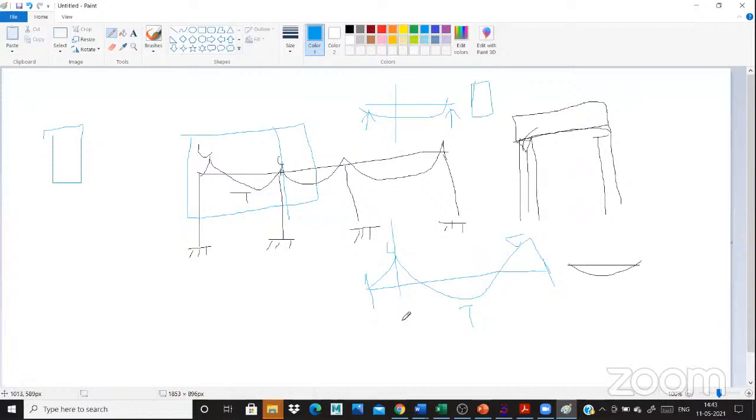The first cross section is for this end, this is AA, our cross section, and the next is the mid span. This is BB for cross section. This is CC for my cross section. See, this is the main concept for your beam detailing. This is a continuous fixed end. The moment will be high in compression, tension, also compression. I take the cross sections as 3: A, B, C. Okay. I draw the 3 cross sections for this beam. This is AA, this is BB, this is CC.